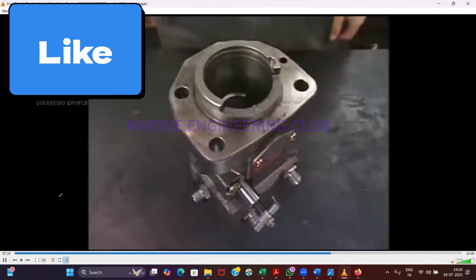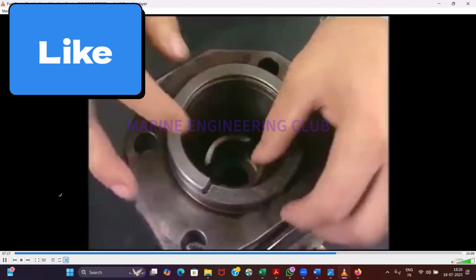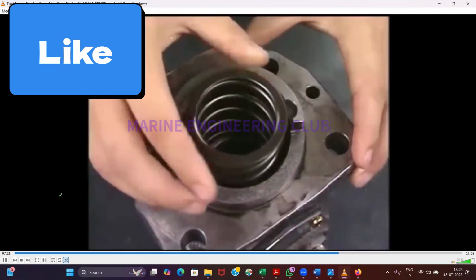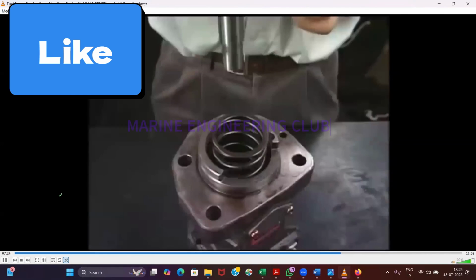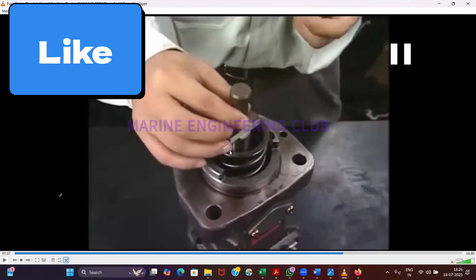And then you will put your lower spring carrier, upper spring carrier. Okay. And then the spring. And then you have to put your retainer along with your plunger. Okay. And plunger marking will be on this side, isn't it? So it will align, automatically align.